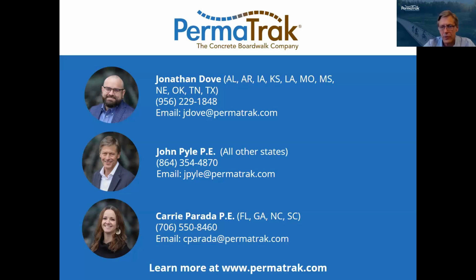But we recognize that doesn't always happen. Sometimes with scour, you get surprised and it comes out. So in this scenario, it would be good for a structural engineer to inspect that location to see what kind of damage has been done. Obviously, the pile's capacity has been degraded. There may be a couple of ways of fixing that, depending on the type of foundation.